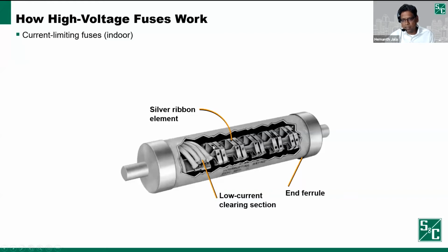At the point where you have these small holes, those are the first areas where, when you have a high amount of fault current flowing through it, it will melt, because that's a small surface area, right? This whole thing is filled with pure silica. And once that element hole melts, you'll have an arc in the place where it melted.